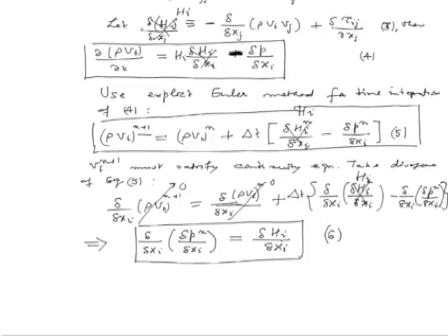So, the steps are clear now. First, let us evaluate this H_i, then obtain numerical divergence of H_i, use that as a source term for the pressure Poisson equation, solve for the pressure Poisson equation, obtain the pressure field, take its gradient and use it in our explicit formula for the velocity components to get our flow field.